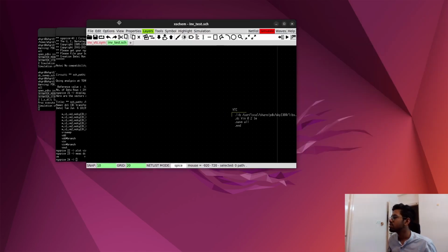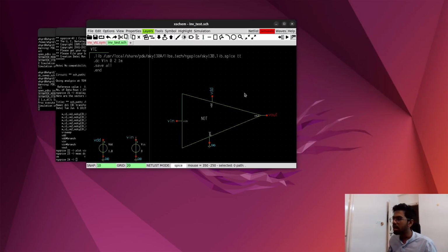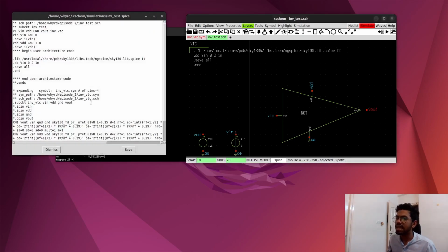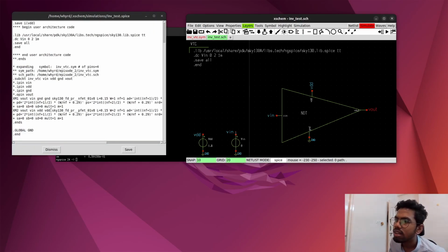Okay, so after doing that, I will again click netlist. Netlisting is done. Okay, in the netlist let us check if it got changed or not. So I'll come here, and you see you have used 2 MOSFETs, M4 MOSFET. One is of this type, and this is your NFET, and here W is 2. Another is of P type, and W is 2. So in the netlist things are getting reflected, so it's perfect.